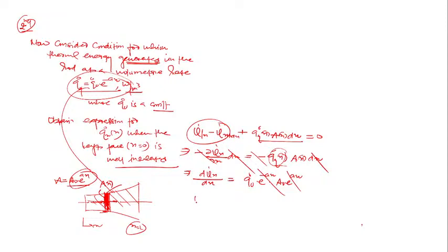Here if you integrate this equation, then I get dq dot x. Let's say if I want to find out, they are asking about flux, how the flux is going to vary with x. First, let's say at any given point x, I just want to find the rate. Suppose first they are asking for the heat transfer rate as a function of x. The heat transfer rate as a function of x is q naught dot into A naught into x plus C1.